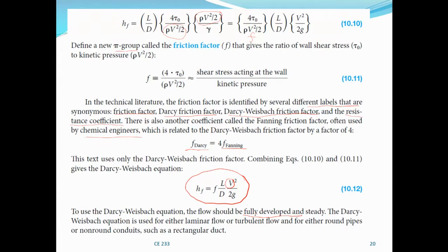Okay, that is when the average velocity doesn't change, it remains constant over time. Okay, and then again, the wall shear stress also remains constant when it is fully developed. At the beginning, at the entrance, like I explained yesterday, the shear stress is maximum at the entrance, and then it will be decreasing because of the reduction in the slope of the velocity profile. Okay, until it becomes fully developed. Okay, that is when you have the minimum shear stress, and that minimum shear stress is maintained.